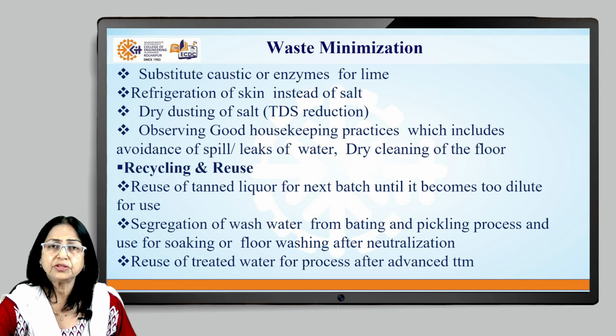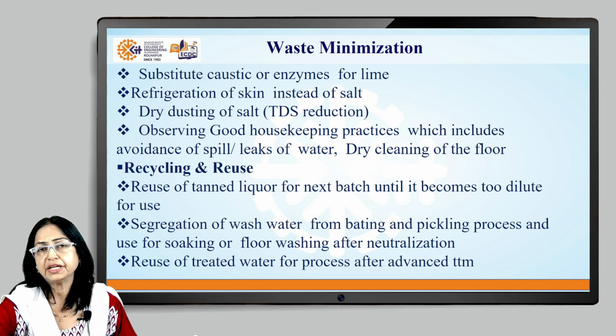Yet another option is, instead of soaking the skin with salt in the soak pit directly, try to dust off or dry remove the salt, which will considerably reduce TDS content. Observing good practices like avoidance of spills and leaks, and dry cleaning of floors instead of wet, is also useful.